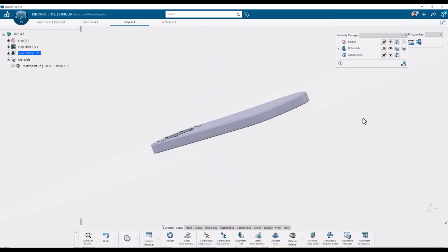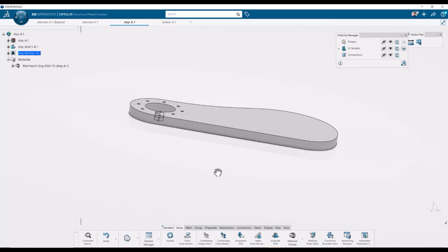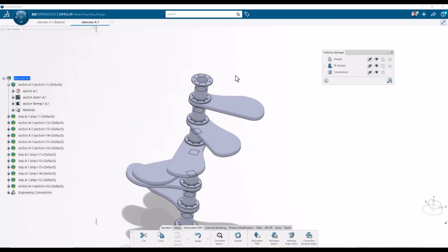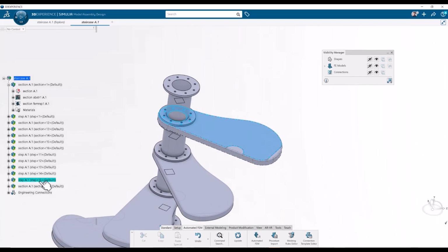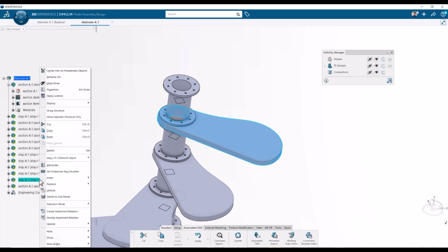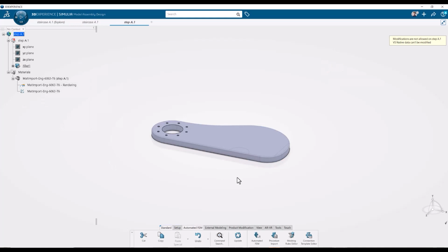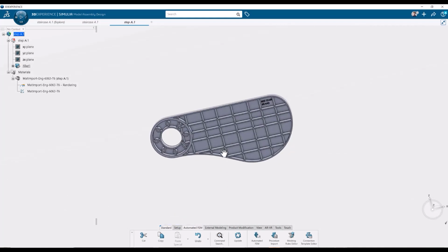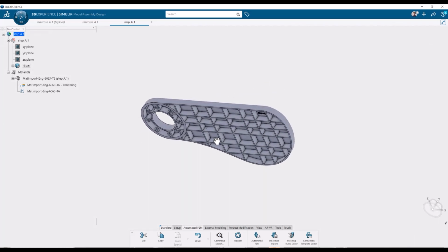In this video I'll show some defeaturing in preparation for meshing with Simulia on the 3DEXPERIENCE platform. Let's defeature and prepare the step part for meshing. So we're going to use an abstraction shape. So first we need to open this one. So I'm going to open the step in a new app, and we're going to do the abstraction shape here. And in the abstraction shape we're going to defeature and take away just a few of the details here.